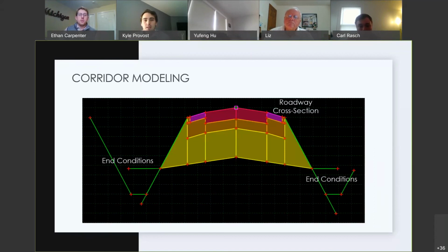This process first begins by creating the template and tying the points within it to specified restrictions based on the adjacent points, including maintaining select grade percentages, depths, and distances. This allowed the template, when modeling, to hold its form, especially when displaying the super elevation sections within the curves.